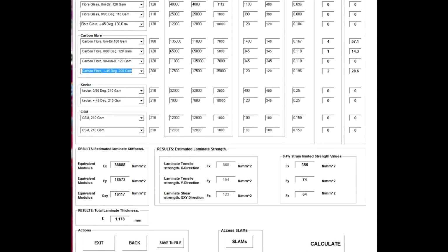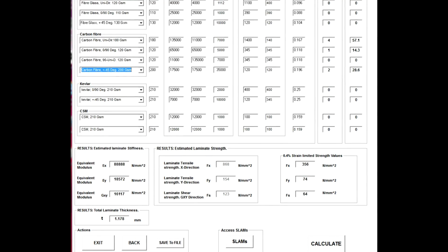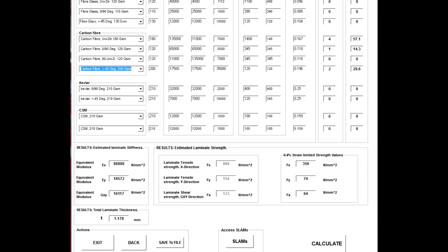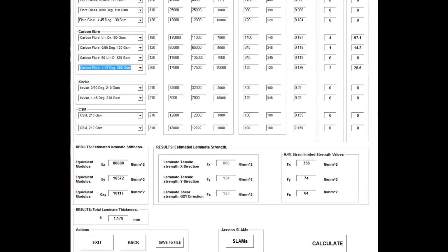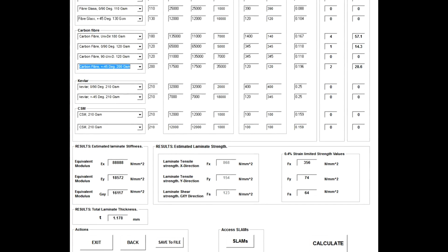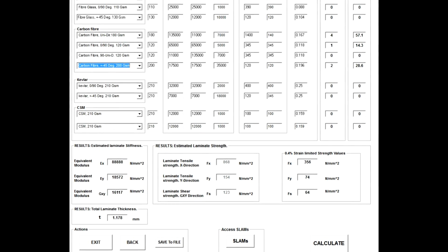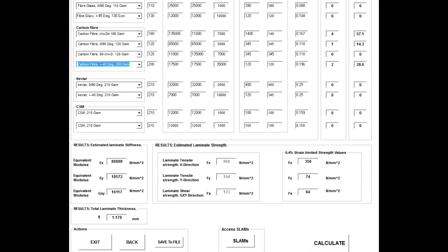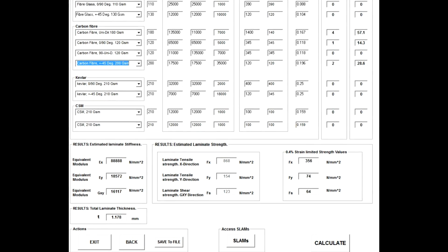Now the thickness of the laminate will increase to 1.178 millimetres from 1.022 millimetres. The composite laminate now will be heavier than the previous laminate design. Don't forget that the material axis of fibre direction 1 aligns with the geometry reference axis of x. So in CSAM, so many parametric studies can be carried out very quickly, like I've just shown you.